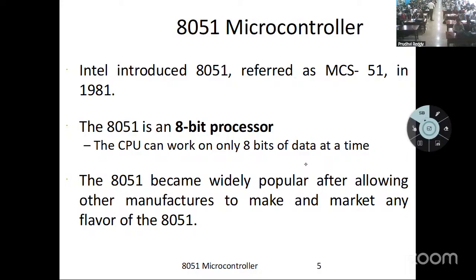If you are using this 8051 microcontroller, you can give data, for example if you want to perform addition. To perform addition, how many operands are required? 2 operands, right? Those 2 operands should be within the range we can accommodate; we can't accommodate 64, 65, 70 or 100 because our size is limited. The 8051 microcontroller has limited registers, and the register size is 8 bits, so that's why we are using only 8 bits of data.